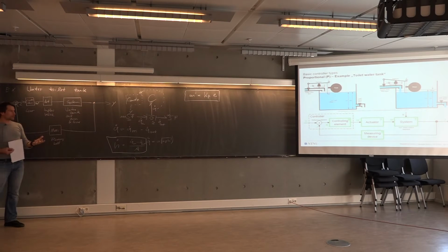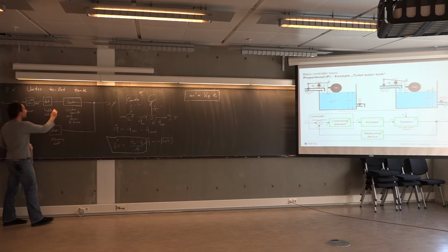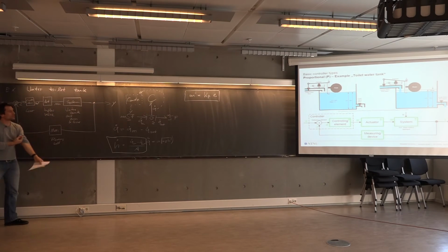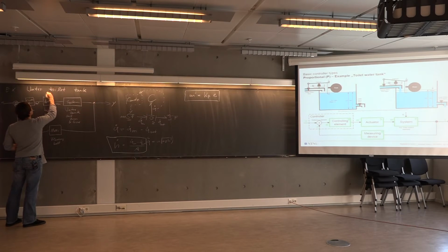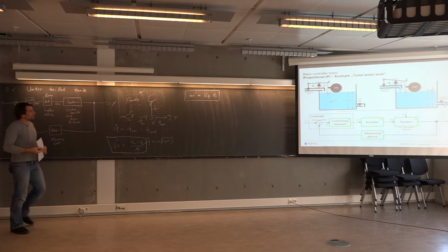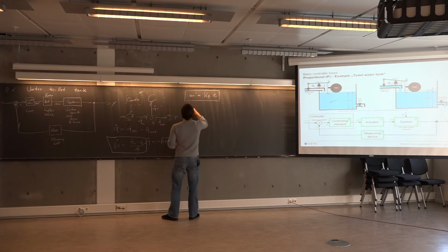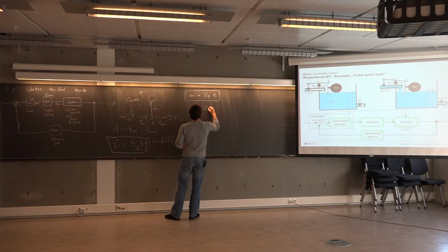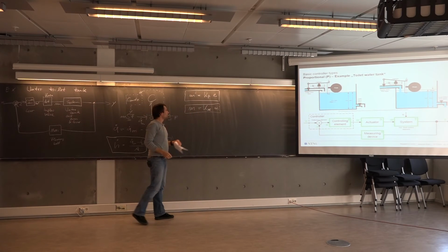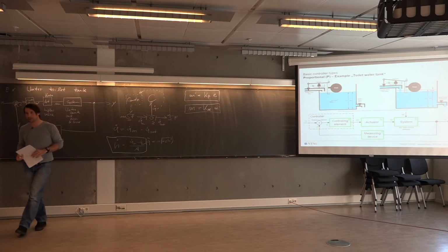With a sophisticated model for this valve, you can translate this to the flow rate, which we actually need. We're going to keep this easy and just assume a linear relationship again and make this a constant value. Let's call that K valve, which means there's a linear relationship between the controller output and the water flow we are looking for.